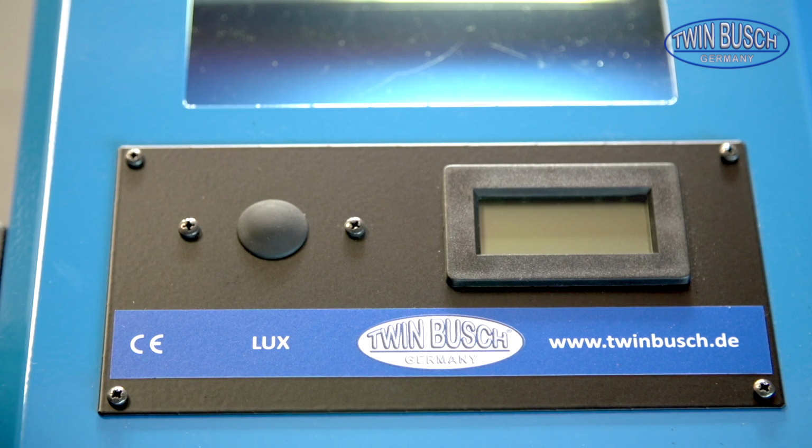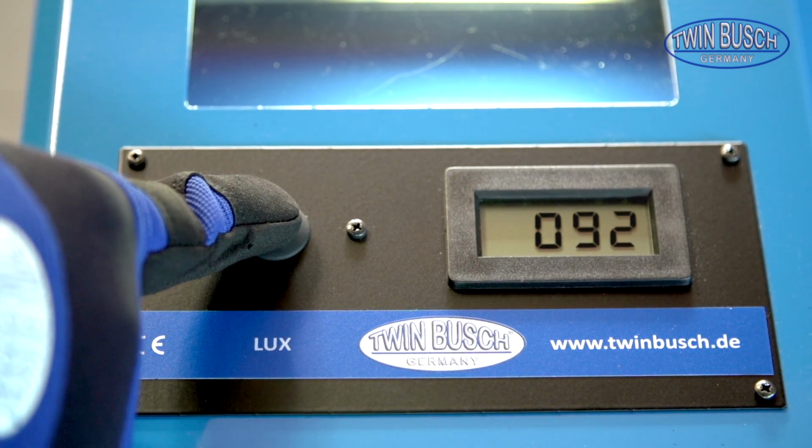For high beams, an oval light beam emerges, the center of which should be on the upper cross, and with fog lights, the light beam should not go over the baseline. We will then also check the luminous intensity.